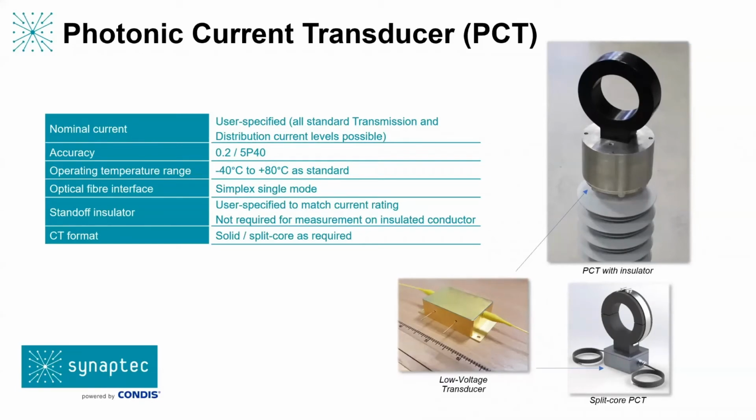Yes, I can certainly jump in on that one, Stephen, if you would like. So the other type of optical sensing, as I think you've said, would be an NCIT, which typically means a Faraday effect current sensor, for example, in which a very special type of fibre is wrapped around the conductor, and then it looks at the rotation of the polarization of light to get a measurement of the current. That's quite a different type of device to ours for a number of reasons.